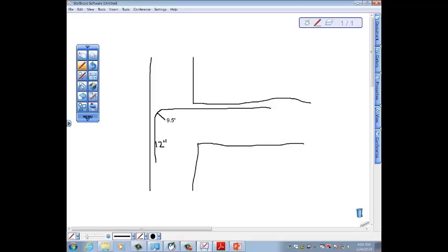Once you get that done, then you're going to draw your bottom bar, which it says on the directions are number 8. So how big are those going to be? If a 9 is 9/8, what is a number 8? 8/8, right. So that'll be a 1 inch thick line, which will be half a square basically. So you'll draw a 1 inch thick line at the bottom. And remember, you'll only see one of them because the other one is beyond your view.